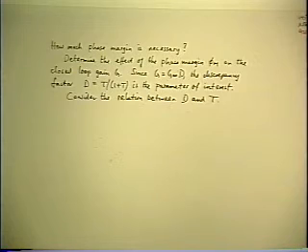Now, even that isn't the only question, because what really matters is not the nominal shape of D. What really matters is the worst case shape of D, because you have a tolerance on the specification and you have tolerances on the components that you're going to build into your system. So what really matters is that you have to meet the specification tolerance under the worst case combination of component tolerances. So what matters is the minimum phase margin under worst case conditions.